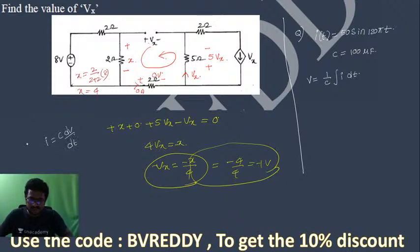Done up to here? So this V value is equal to V of 0 plus 1 by C integral from 0 to the present time of I into dt. In the problem, V of 0 is given as 0, so there is no problem.